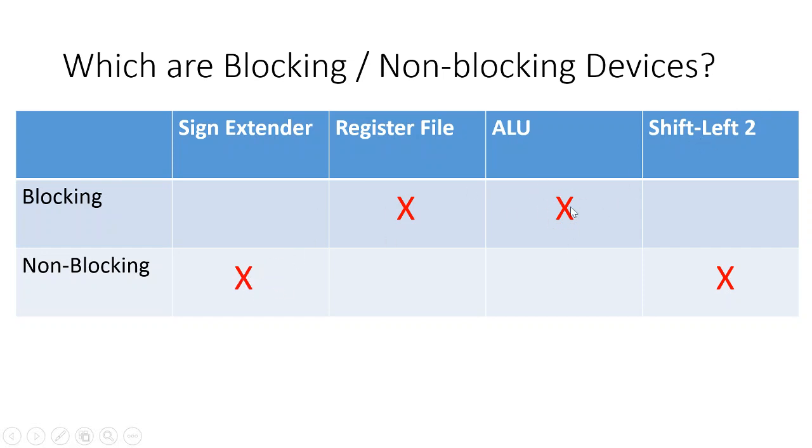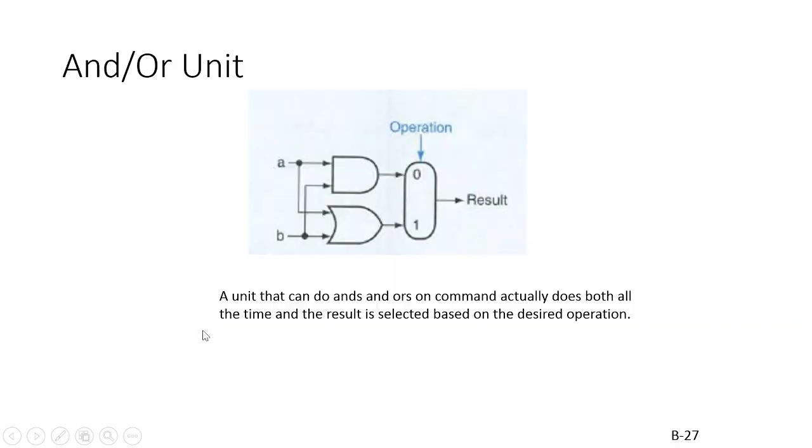There's really no data storage occurring. But the ALU may have a previous state, and the register file, definitely the register file, we're going to talk about in a little bit, is just a register. There's data being saved in there. So there's sequential logic in these, whereas these have mostly combinational. It's not even really combinational, it's very simple logic.